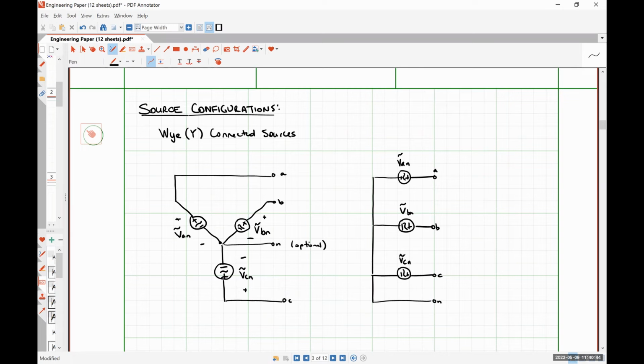I want to talk to you about something very brief here. The double subscript notation that I'm using, I talked about this very briefly at the beginning of Engineering 221 for those of you that had me. When using this double subscript notation, the first letter in the subscript references the positive polarity terminal, and the second letter represents the negative polarity terminal of the element in question.